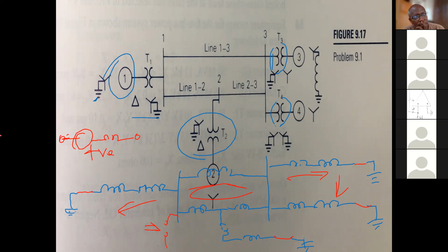And let me go further. In terms of a power system, for two faults to be happening simultaneously, for you to be forced to analyze them, they would have to occur at exactly the same time, because your protection system works in milliseconds. All right, sir, you with me?